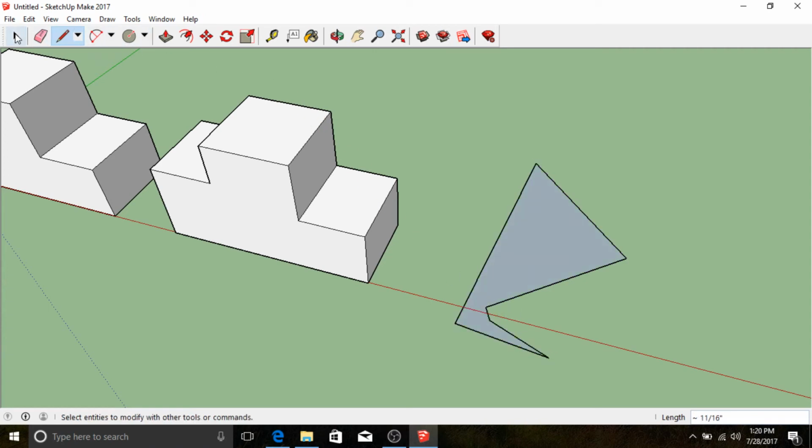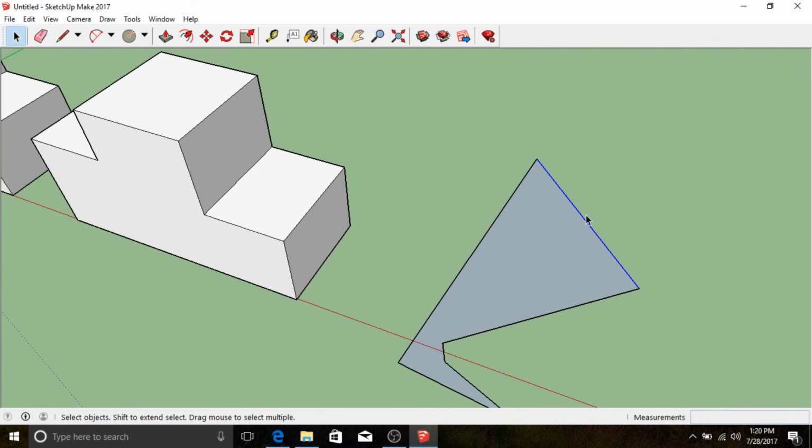And it's the select tool and the way that the select tool works. So the select tool is what we use to select any given entity or entities. And in order to select multiple entities and making sure you're selecting things correctly, you really need to understand how it works. So if you notice, when I clicked on this edge, it turned blue. That means that this edge is selected. If I click on another edge, the original edge becomes deselected, and I've now selected this new edge. If I wanted to select both, I can hold Shift to add to my selection.